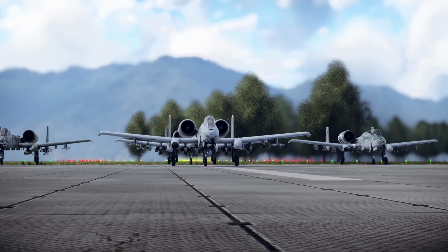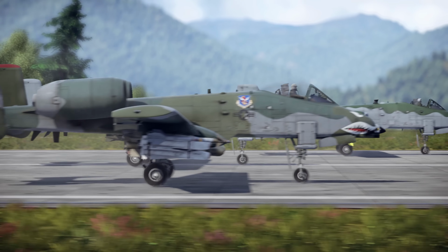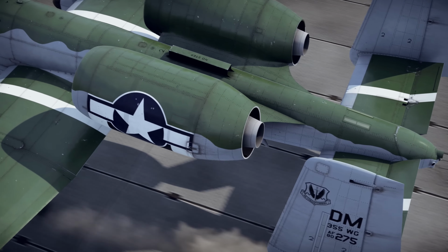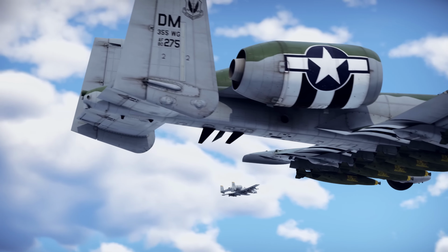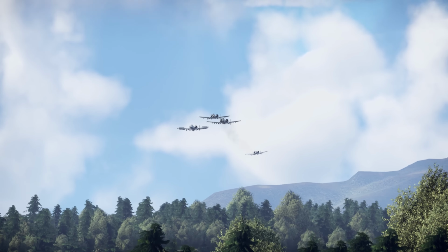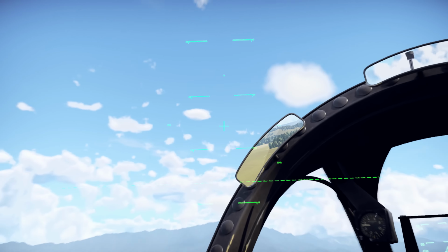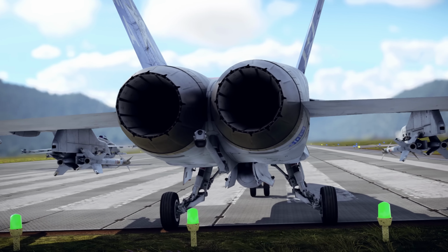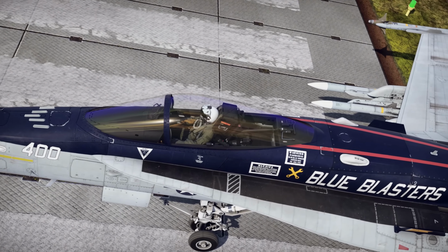The large front fan is essentially a low-pressure compressor, but it's a prominent enough feature to warrant the turbofan name. You've certainly seen such engines on commercial airliners, and in War Thunder, the clearest example is the A-10. Up to 80% of its total thrust comes from the bypass flow alone. This becomes possible thanks to the massive volume of air going through the ducts. High bypass engines are quiet and fuel efficient, making them ideal for subsonic civil aviation. But that same huge fan creates enormous drag at high speeds, making such engines unsuitable for supersonic fighters.